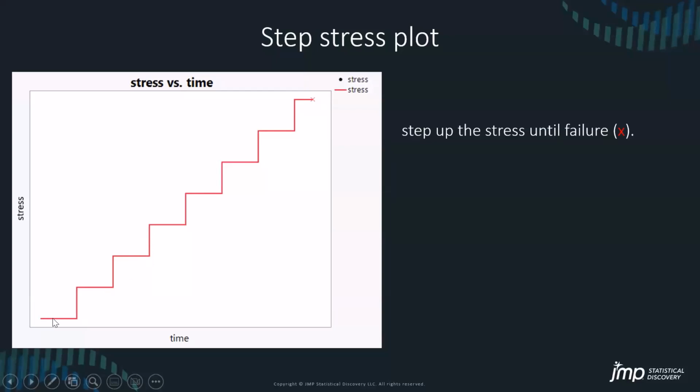And I start at some very low stress for some amount of time. Then I quickly up the stress, and then I hold constant for some amount of time. And what we're assuming is when we change the stress like this, that doesn't have any effect at all. And that may or may not be a good assumption. So you'd have to be very confident and comfortable that if I change the stress a lot, it's not going to have some new additional influence, right?